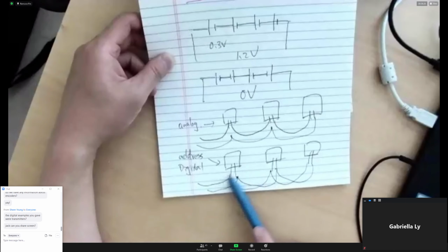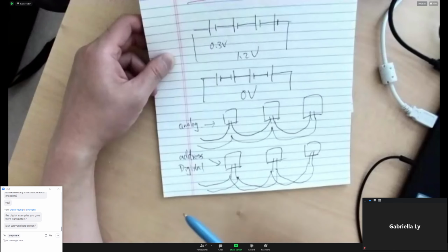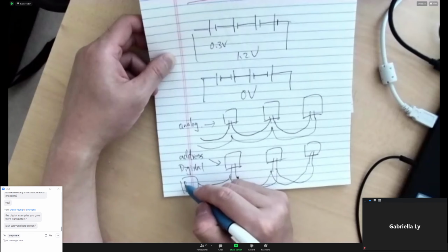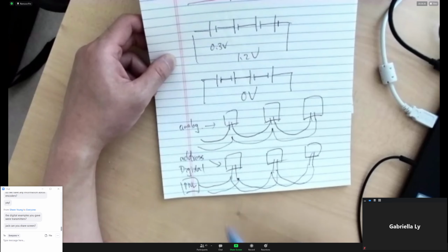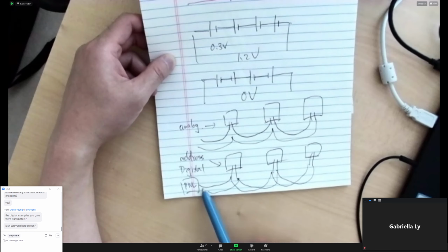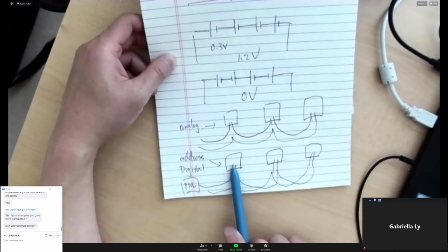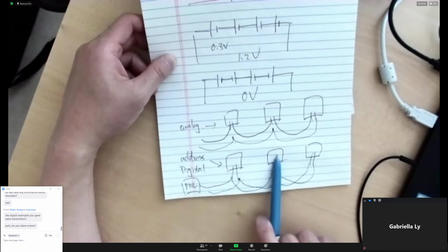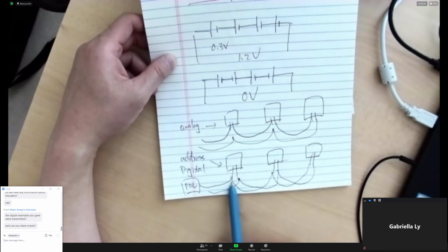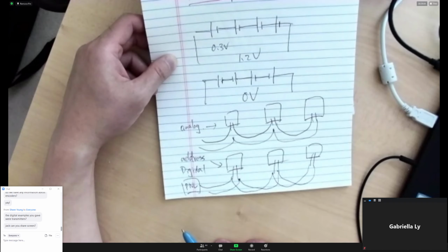The addressable system is from your fire alarm panel. It will talk to each device using one of the communication protocols. They just have one bus. The panel will say, okay, I want to talk to the first device. It sends the address out, the first device will be online, and they will communicate. Then if the panel says, okay, I want to talk to the second device, the other devices will be quiet. Just the first one will be communicating with the panel.